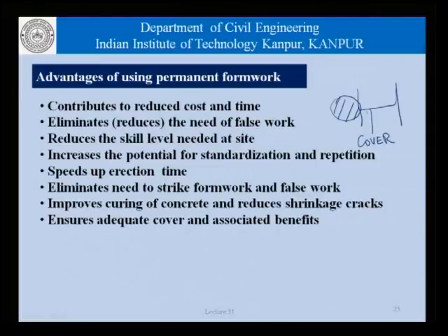And if beyond this point we have a permanent formwork of a certain amount of thickness, now whether this thickness of the permanent formwork is to be counted towards the cover thickness or not is a decision which the designer has to take. It has to have certain sanction as far as specifications and design methods is concerned, but nonetheless it should be borne in mind that at the end of it, this permanent formwork is also contributing to protecting this reinforcement from the environment outside.